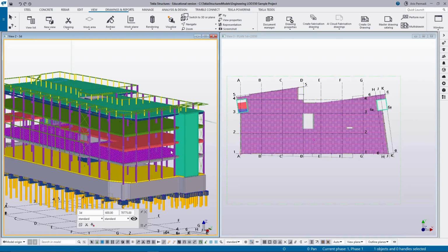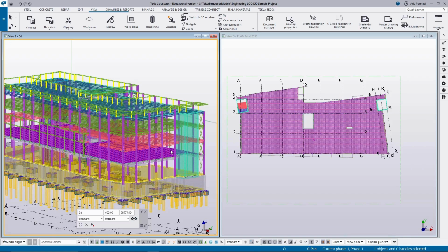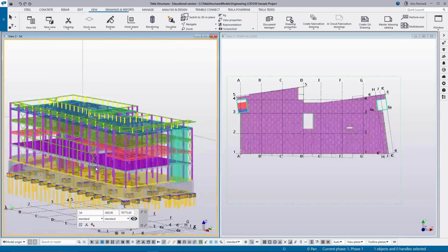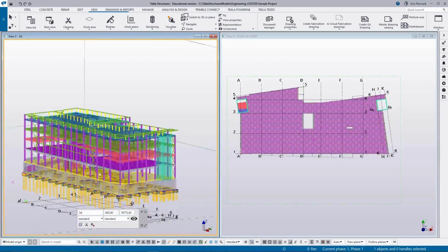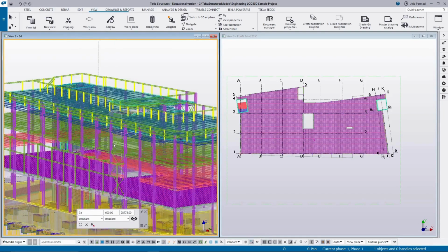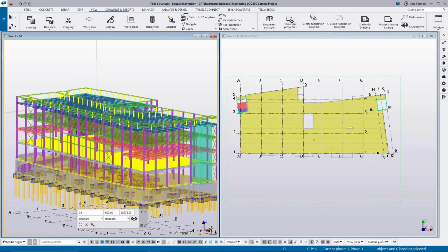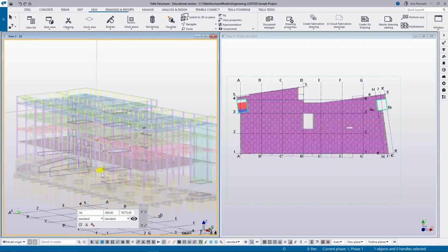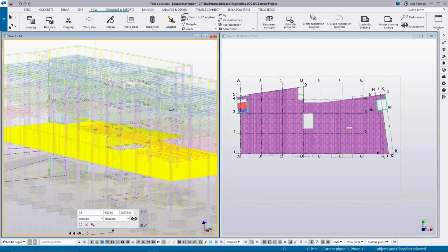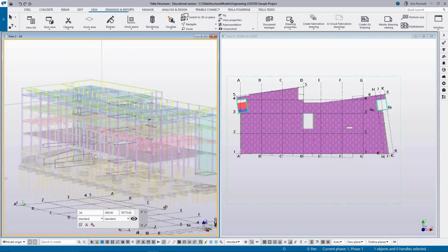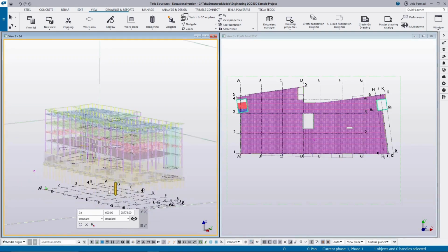But if you want, just touch the Ctrl+2 button, you can see through the walls, or see through the objects. And Ctrl+5, you can clearly see through the objects like this. Okay, that's how you manage the visible objects.